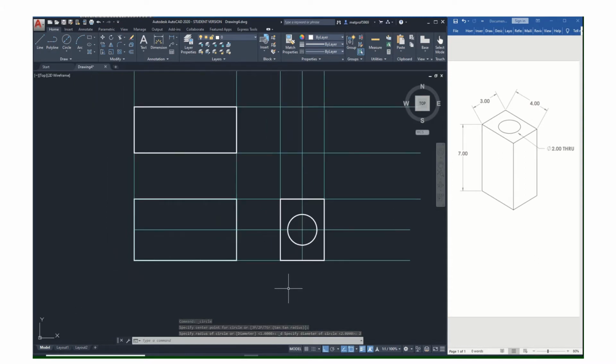Now, what does that do for us here? Now, it really helps us see what's happening here. So in this that I've chosen as the front view, now I know just to the naked eye you see this surface, but we want to reveal the other features that exist in that part that you can't see from that particular point of view. So that's going to be some hidden lines and center lines to show that there's a hole here.